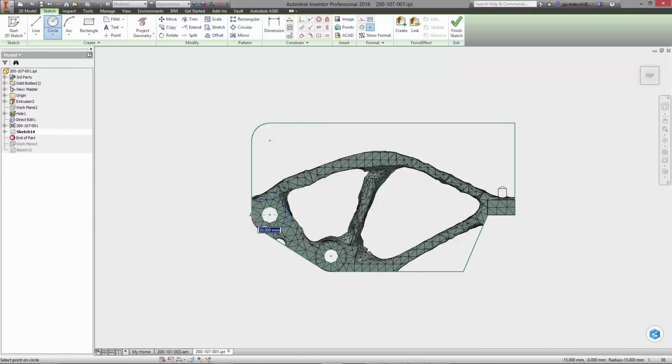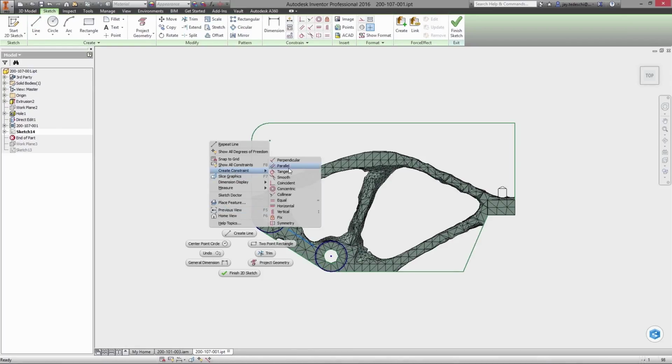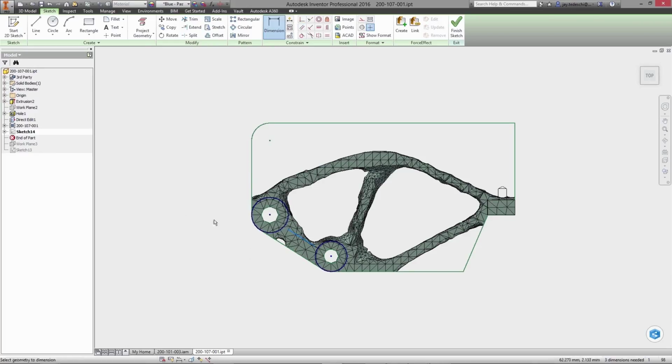This generative shape is then merged with the initial model volume, and then any one of a number of modeling techniques can be used to remove material from the volume, leaving the minimum amount of material required to match the results defined by Shape Generator.